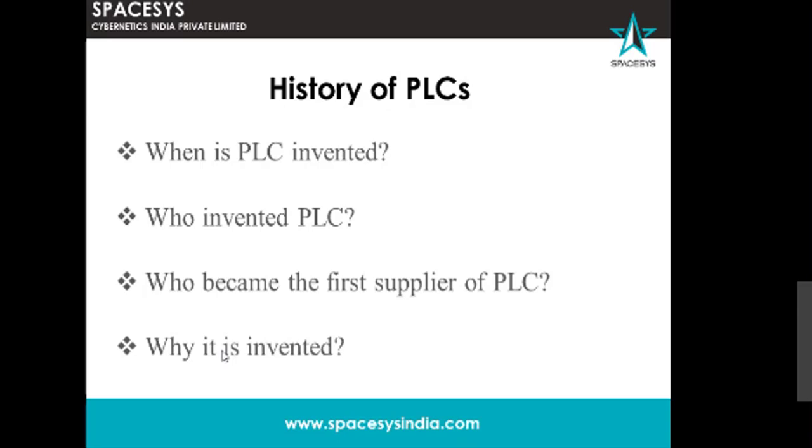Why was it invented? As I told before, PLCs were designed to overcome the limitations of relay logic. Relay logic is made of many mechanical wires. It makes it more complicated to find a fault when one occurs, and adding external devices is also very difficult. It would require a technician to rewire the whole setup. Also, it requires more space for the components that are connected to it. But PLCs are much smaller as they have controllers within the software itself. So by considering all the drawbacks of relay logic, PLCs were invented.